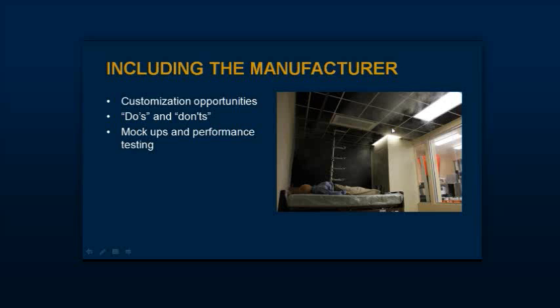If I have a building built 30 to 40 years ago, there is most likely not a significant vapor barrier, or if there is a vapor barrier at all. Buildings built in that era and earlier often had a large amount of natural infiltration through them, sometimes as much as 30 air changes, more commonly perhaps 20. In today's buildings, we have about 6 to 4. So we've trapped the moisture, we've kept it from migrating through. So if I'm looking at the two technologies that I've stressed a lot, chilled beams or displacement probably would be a little more at the front in the building if we're not going to change the envelope and put in a vapor barrier, or we're not going to do some sort of pressure control for vapor.